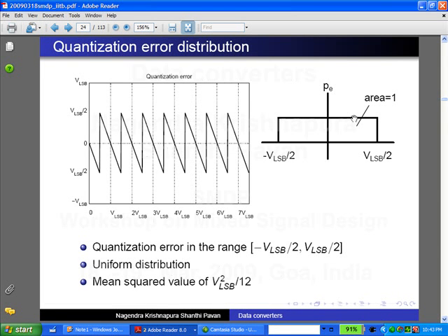Yeah, surely. You can find that. So we will come to later what other errors you will make. So far I am talking about the errors inherent in quantization. It's not a mistake I am making. If I build an A to D and make some mistake in a design, I can get other errors. But this is not a mistake. The moment you quantize, the moment I say rounding off, I will be making errors. That's the thing I am talking about.